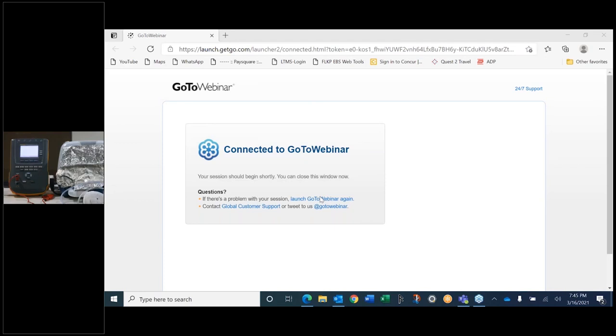So you would set this to IEC 62353, and then while you're doing your electrical safety testing following the menus on our safety analyzer, you would use the direct method or the alternative or differential, whichever one of those you selected, not all, just one. Okay. And yes, that's how you make sure that your testing is compliant to the international standard in an appropriate way.